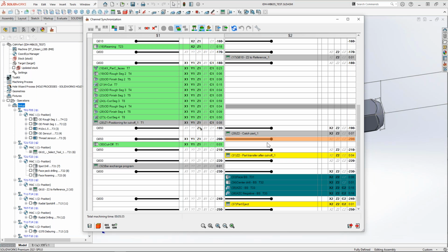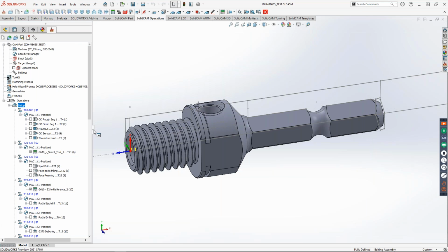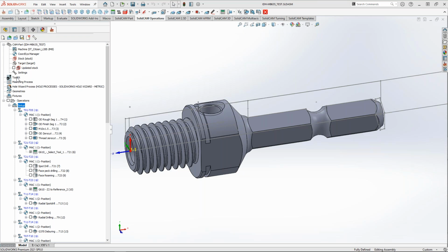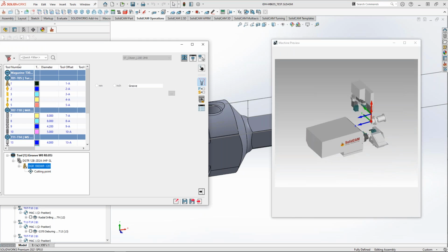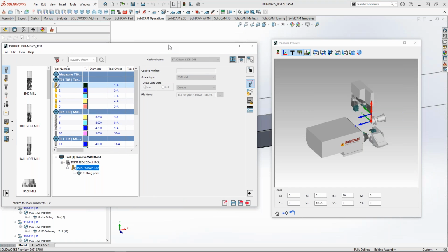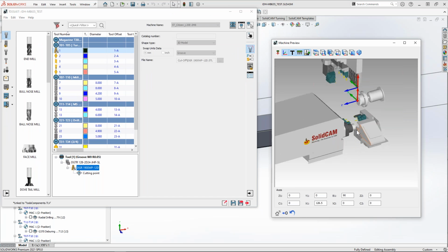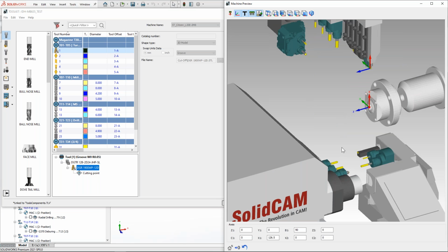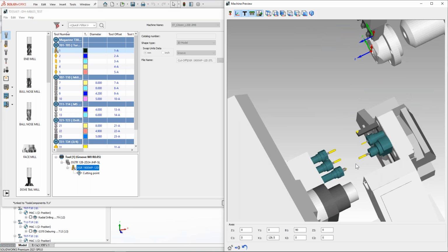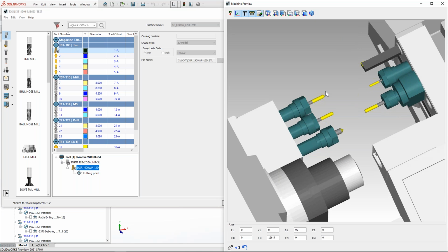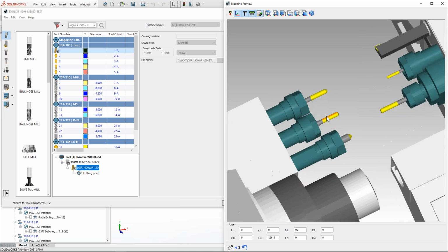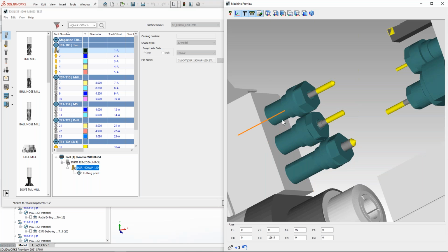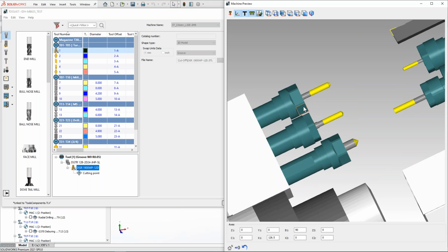What I also liked here, let's go back to the tool table itself. And for all of you who work with STL holders, I'll just zoom in here. So this is the Swiss type machine over here, L20 to M8. And I would like to talk about these tools over here. Now here we have three long drill tools, and as you can see, they are of different length. So the outside holder length is calculated differently.